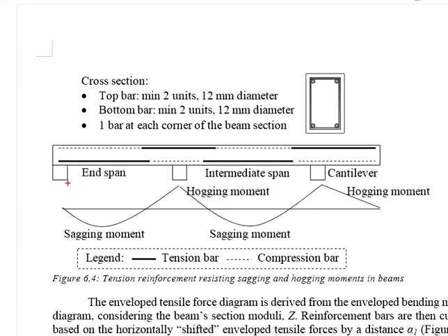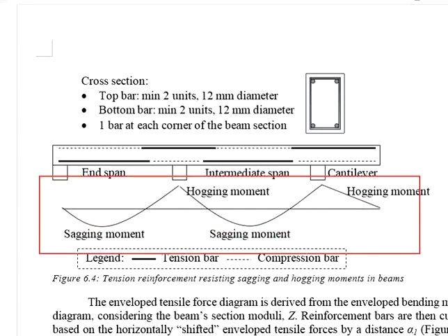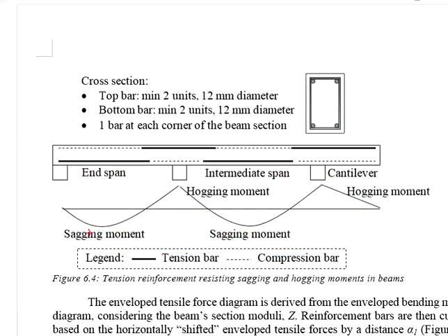However, if you observe the typical bending moment diagram, you will see the moment reducing along this span. That means near to the end support, there will be less moment and less amount of reinforcement bar is required.